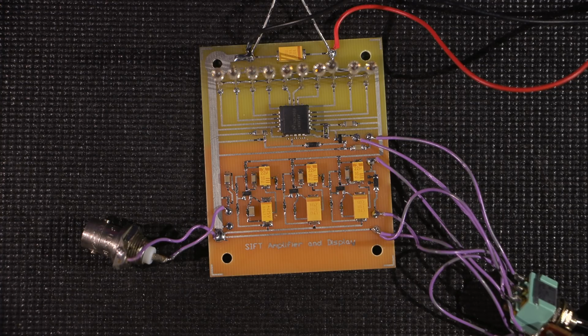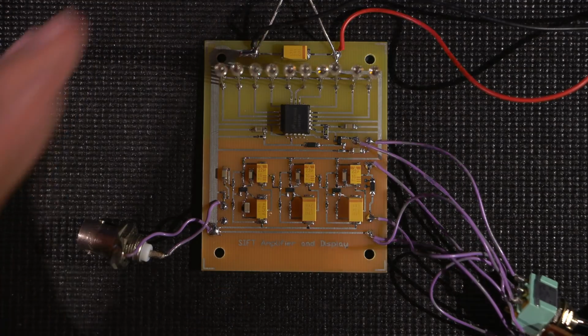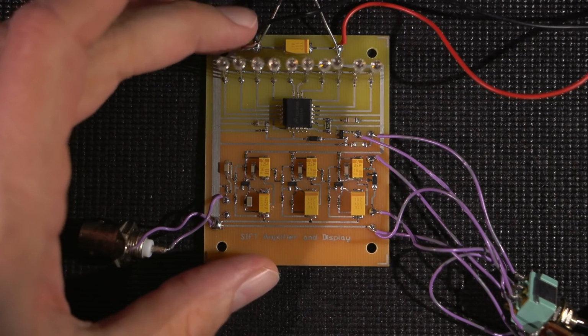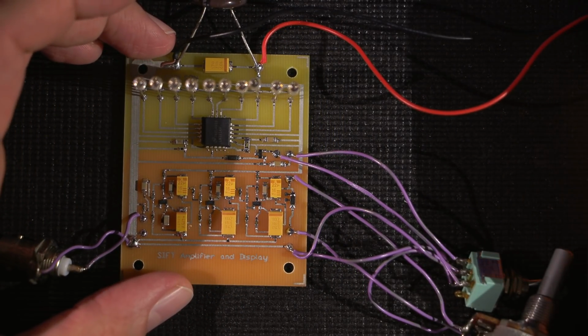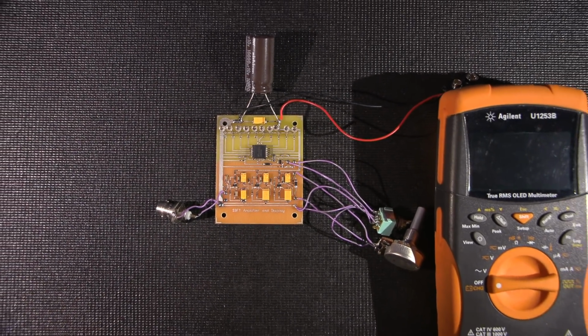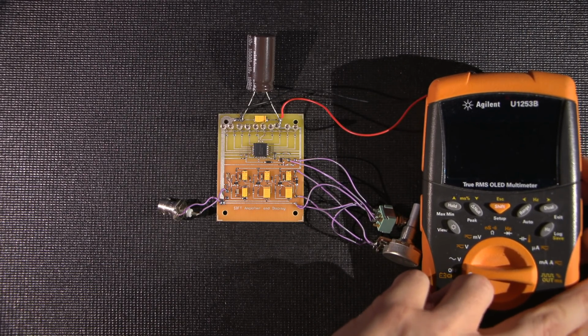So now, if you want to very quickly verify what you have here and how it's hooked up, because at this point we wouldn't know if this was an unknown design, we wouldn't know if that was, as I say, a FET or a PNP, NPN, whatever they've put in here, right? So you want to grab a DMM. I have a video on YouTube that shows how to do the check here with just a standard diode checker. So what I'll do is I'll just back this out until I can get my multimeter in here. There's quite a bit of glare on this. If I can put something under here.